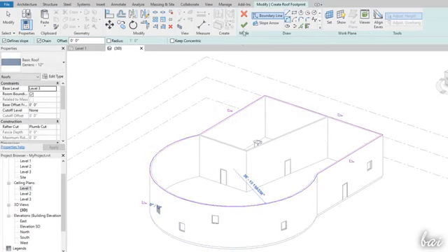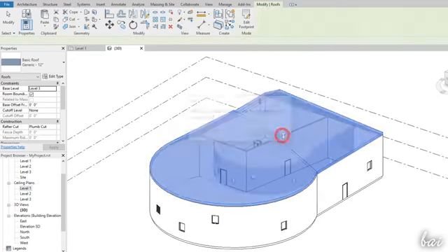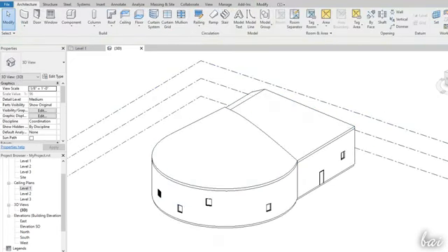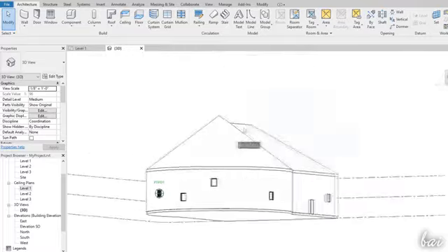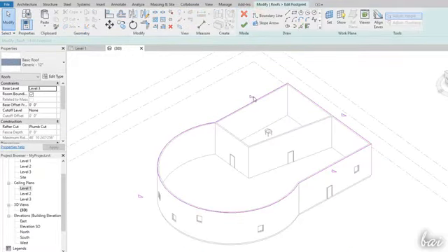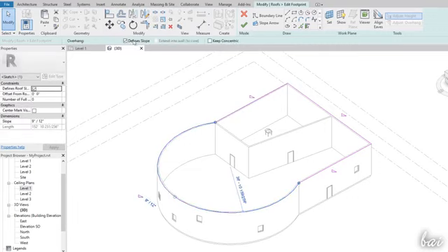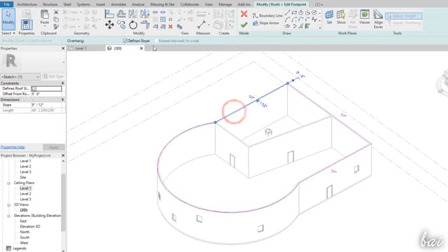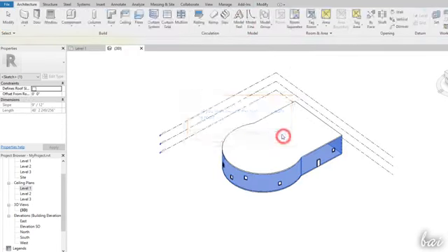When applied, the roof is created by adding slopes on each of its base sides. This is made automatically as long as you have Define Slope enabled for each of the sides that show a triangular icon. If you create the roof with no slopes at all, this will be completely flat,